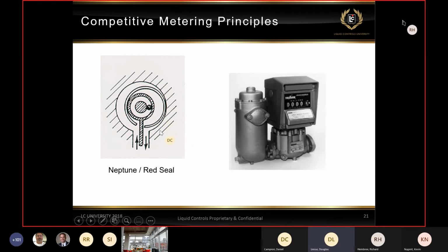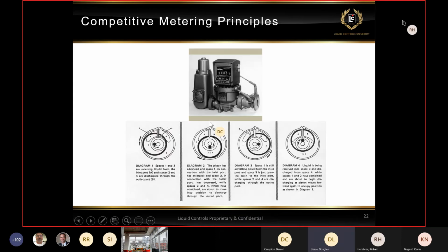The wear points are certainly where it touches this wear plate, and also this hub, which is a bearing that's going to be rotating around this open circle area. As those begin to wear, their accuracy becomes less and less, because what they're trying to measure is this chamber that's here. And I'll go to the next slide and you should see a better sequence representation of it.